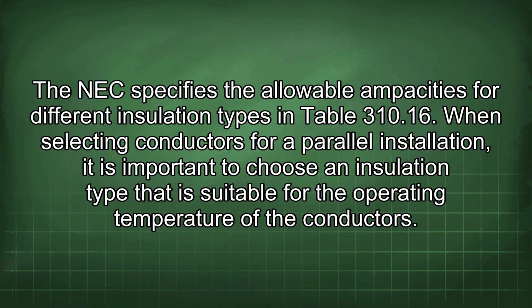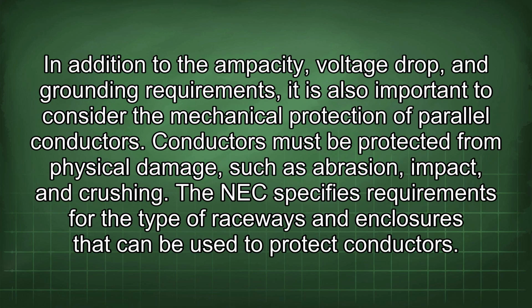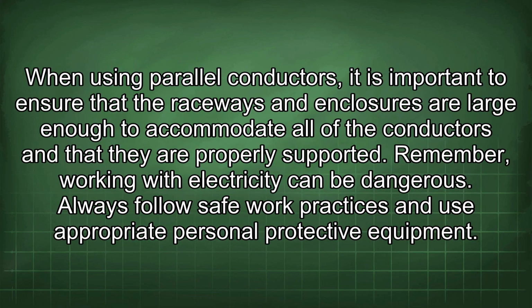When selecting conductors for parallel installation, it is important to choose an insulation type that is suitable for the operating temperature of the conductors. In addition to the ampacity, voltage drop, and grounding requirements, it is also important to consider the mechanical protection of parallel conductors. Conductors must be protected from physical damage such as abrasion, impact, and crushing. The NEC specifies requirements for the type of raceways and enclosures that can be used to protect conductors. When using parallel conductors, it is important to ensure that the raceways and enclosures are large enough to accommodate all of the conductors and that they are properly supported.